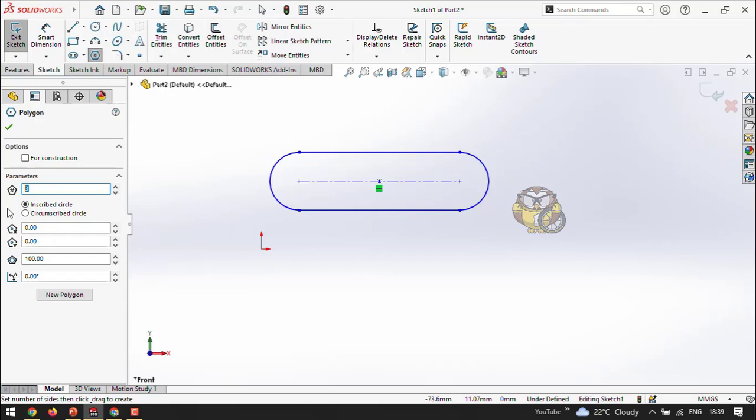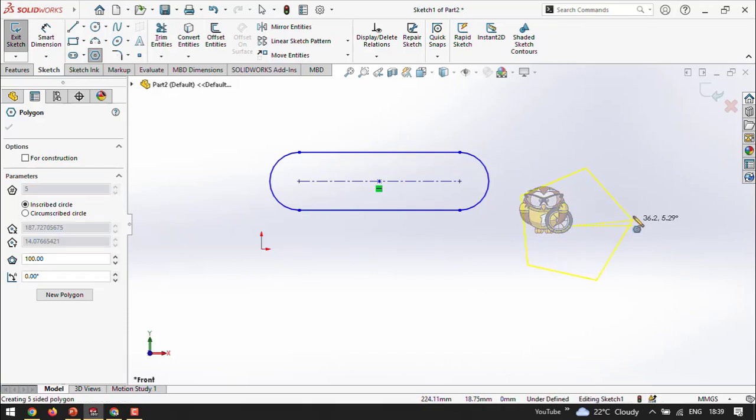So now I am going to give a 5-side polygon. Just I go to give the polygon side, and also those are completed in AutoCAD, they know very well. Inscribed circle, circumference circle. I think I no need to explain here because you are familiar. So just I go to select the first one. Next I go to select the midpoint and just track my mouse. See, once I select the midpoint and track my mouse, now I can see how many sides in my polygon, and also I can choose the angle.